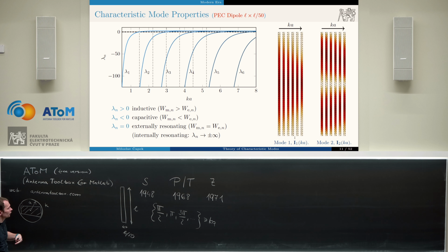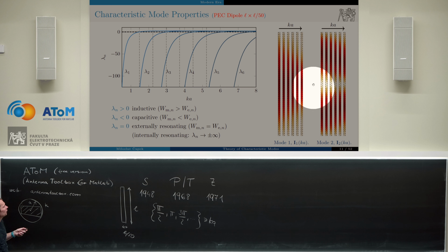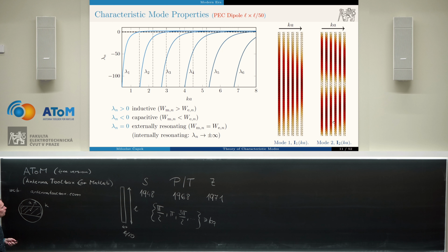It's changing its shape with frequency. So we cannot consider it being constant, by no means. And for completeness, the same is shown also for the second mode here. And you can see that the first mode is basically one sinus wave like this. And the second mode has 2 sinus waves like this. So these are the classical modes on a string.